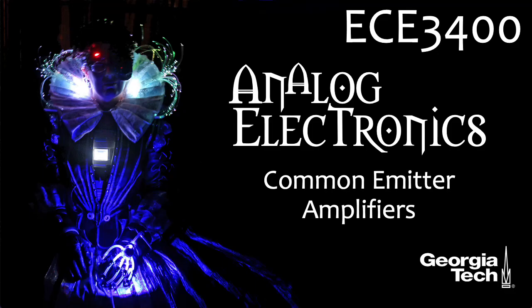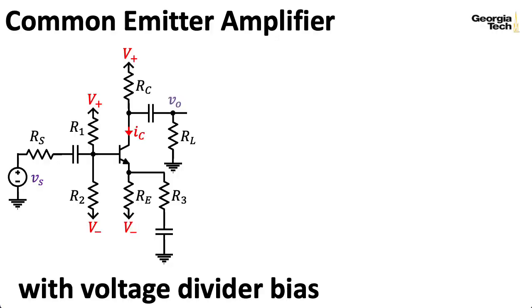In any case, all of that hard work is now going to pay off when we analyze some amplifiers, and we'll start with the ubiquitous common emitter amplifier. So the kind of amplifier I'm going to explore here uses a fixed bias scheme. This is fairly common, and basically I'm considering the amplifier itself to be this part of the schematic here between and including these capacitors. The job of these capacitors is to basically act as DC blocks, so we can have some internal bias voltages that differ than what is being used by the outside world.